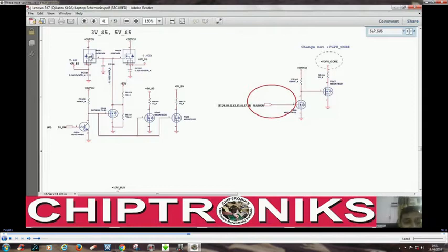Now this is again an N-channel MOSFET, the gate is connected with 15 volt, and the voltage at the gate is higher than the voltage at the source, so this MOSFET will turn on, and this +3V_PCU will come to the source, drain to source. So this 3V_S5 is generated from this +3V_PCU when this gate is activated.